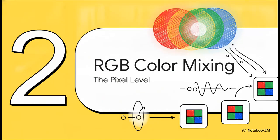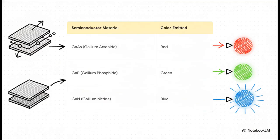Moving on to Section 2. RGB color mixing principles at the pixel level. Okay, so the physical material of the semiconductor substrate literally dictates the exact wavelength of the light emitted. We aren't just slapping colored filters over white bulbs here. Gallium arsenide physically produces red light, gallium phosphide gives us green, and gallium nitride gives us blue. These are our essential independent building blocks.